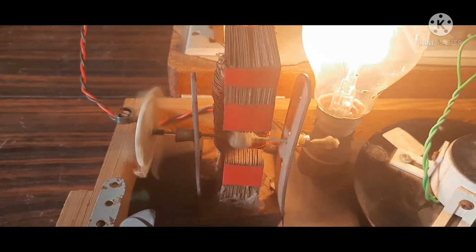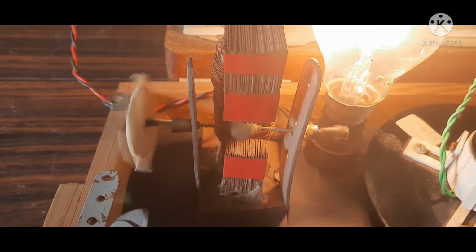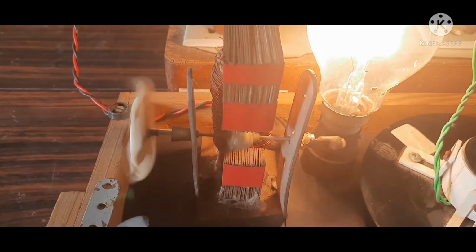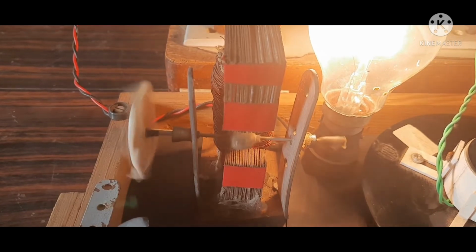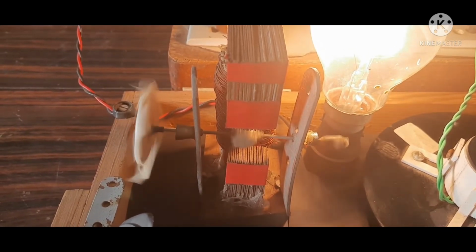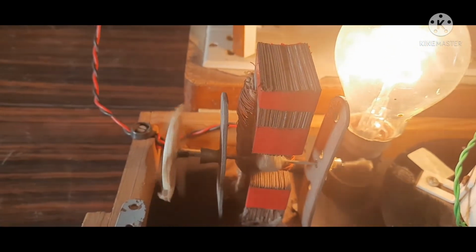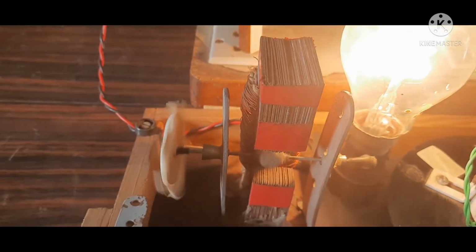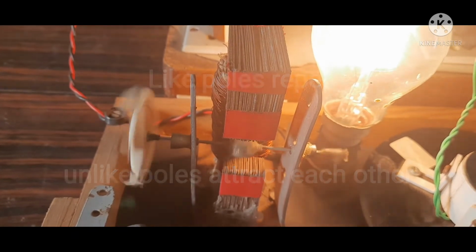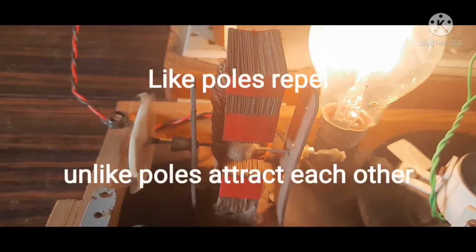So here you are seeing that this is acting as a motor. When current is given to the circuit, the coil produces a magnetic field. Then in this neodymium magnet also there is a magnetic field. Both magnetic fields interact, and you know, like poles repel, and unlike poles attract.